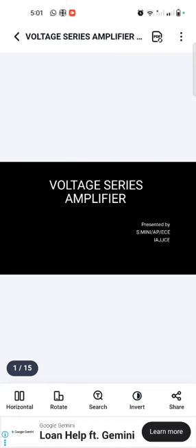This feedback can be used to control and stabilize the amplifier's performance, right? Then why is this feedback used? It improves stability, reduces distortion, and the gain is also controlled. The bandwidth is increased, and it reduces the effect of component variation.